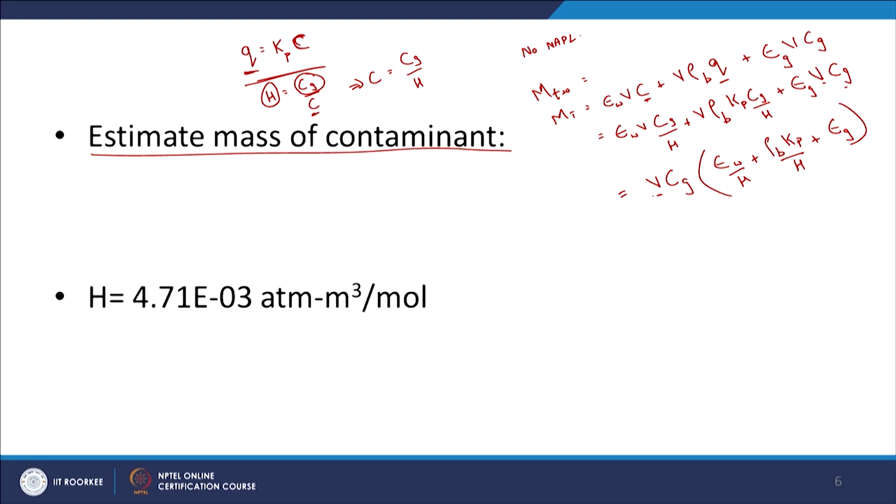Obviously, I need to calculate the volume out here, right. So, again Henry's constant from the relevant literature is out here, but as you see, what are the units here? This is the case when Henry's constant is equal to partial pressure of the relevant compound in the gaseous phase by the relevant concentration in the aqueous phase. Why is that? Because the units are atmospheres per moles per meter cube, let us say, right. That is what we have out here, right.